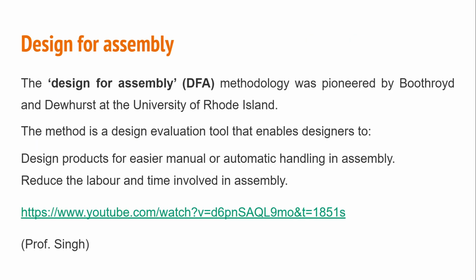Design for assembly. Design for assembly is a methodology pioneered by Boothroyd and Dewhurst at the University of Rhode Island. The method is designed to enable designers to evaluate products for easier manual or automatic handling in assembly, and to reduce the labor and time involved in assembly.